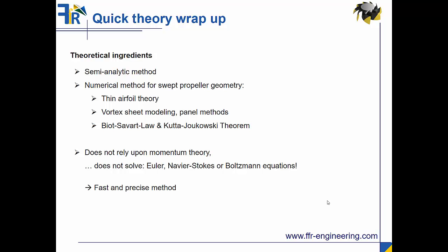And very often the advantages of having such a momentum theory based system like CFD are erased by not taking care of flaws in your computation, from having bad ratios in some of your elements in the boundary layer and so on and so on.